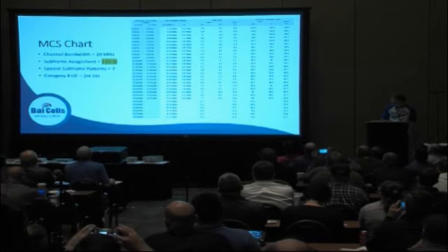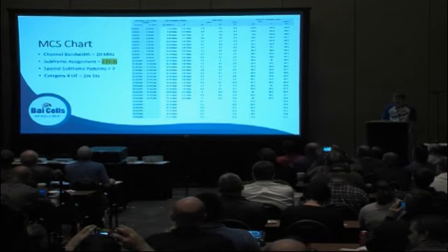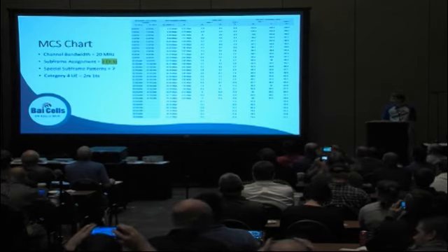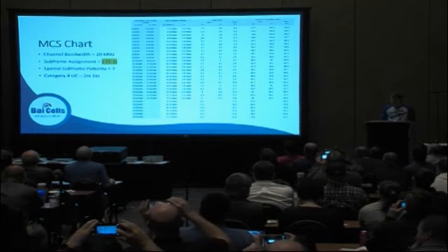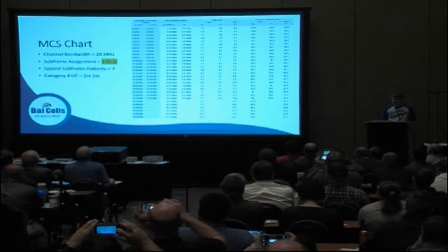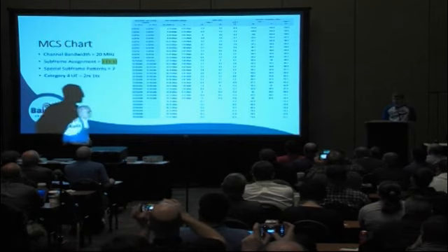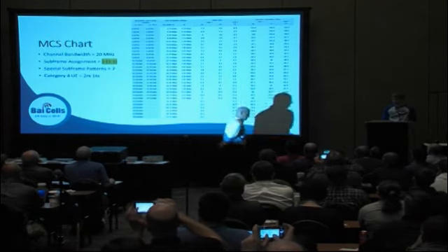Hold on that one for a little bit, and maybe spend a little time talking about what minimum levels people should be considering. We'll hit on that a little bit later, but obviously, you usually want to hit 28 on the MCS for the downlink.